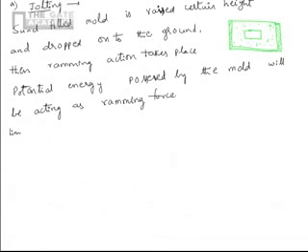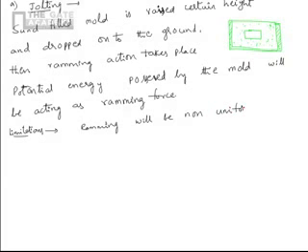So, limitations. The top of the molding sand will be loose sand, so the ramming action will be non-uniform throughout the sand mold.